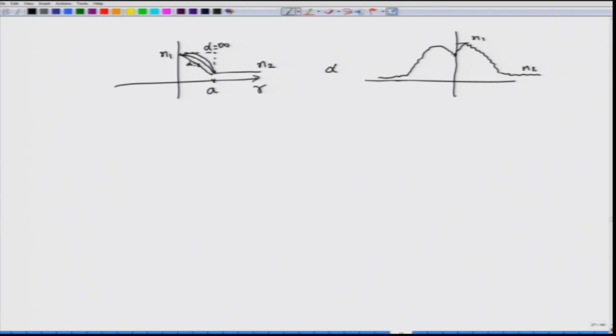Of course, this dip is unavoidable because of the manufacturing problem, and also notice that the refractive index is not a smooth curve, but rather has jagged edges. That is because the refractive index profile, despite whatever manufacturing improvements we have made, is not really a smooth profile. Surface roughness, if you were to examine it, would give you a jagged refractive index profile.